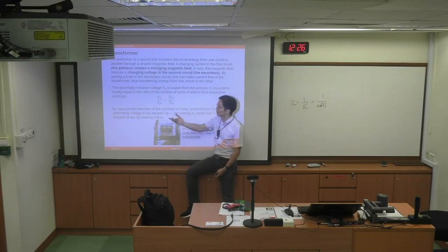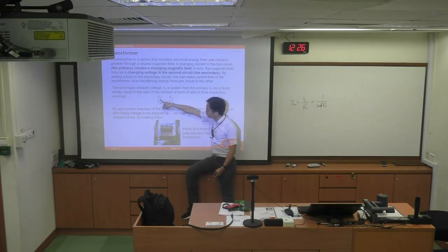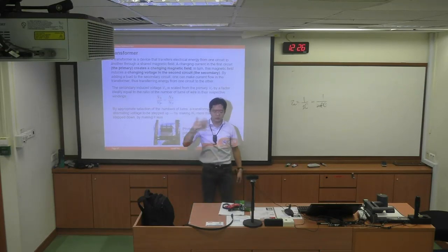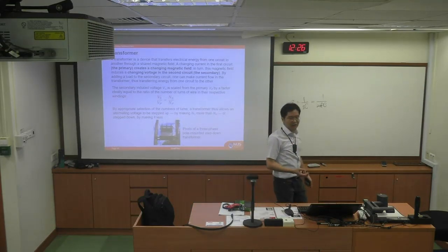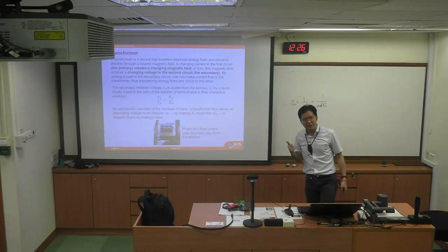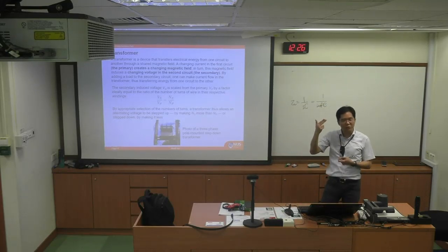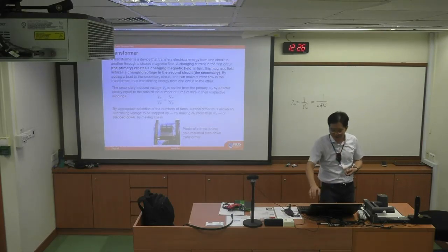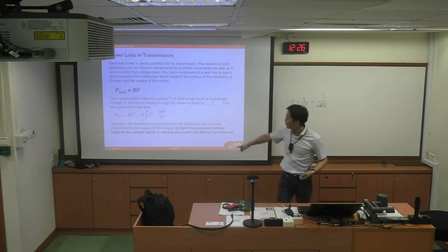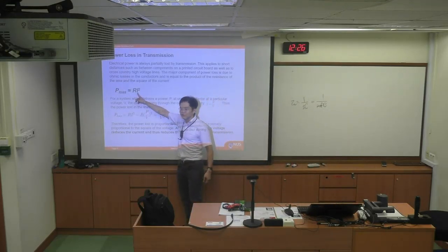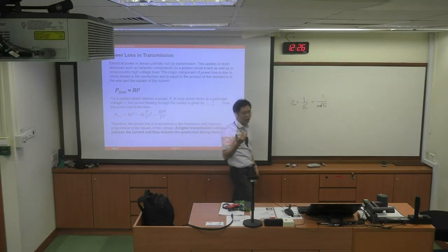on that side. So in other words, if you have the primary to secondary turn ratio of 1 to 100, then the secondary voltage will be boosted up by 100 times. Then what do you think we will be losing? If you increase the voltage, what do you lose? Current. That's the key thing, right? We increase the voltage to decrease the current proportionally so that the power loss will be less.